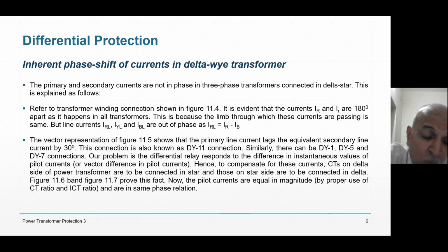Induction motor speed you can change from minus 1440 to plus 1440 in very small steps, using power electronics, using thyristor drives. But those thyristor drives are very non-linear. That means there are heavy harmonics in that.